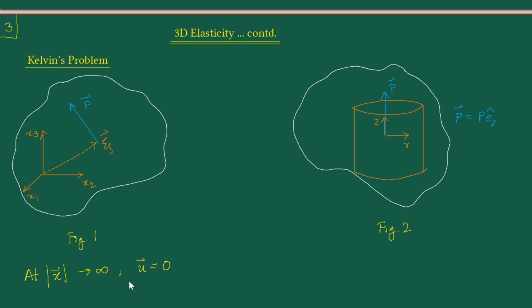Please note that I am specifying my boundary condition, or whatever this far field condition is, in terms of the displacement vector. I am not actually writing this in terms of the b vector or the beta vector, because those are things which are part of just the Papkovich-Neuber representation, which helps me to proceed with the solution. Ultimately, the problem that I'm solving for is to find out the displacement vector. So whatever conditions are imposed must be utilizing those things.